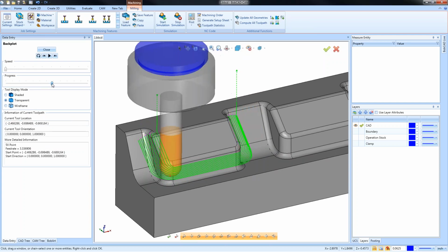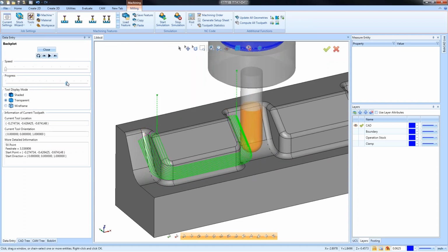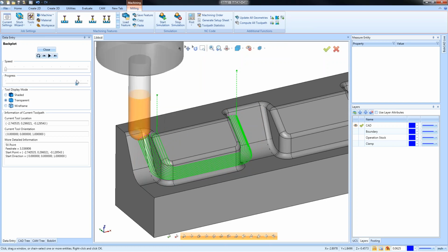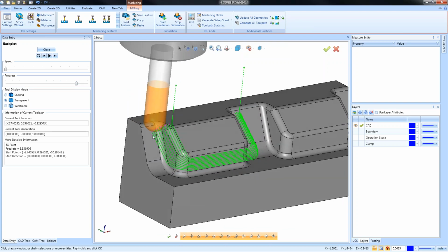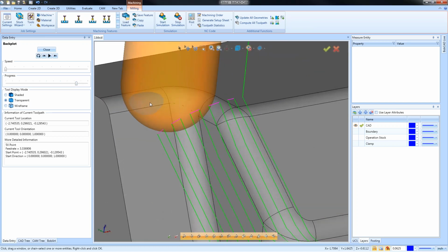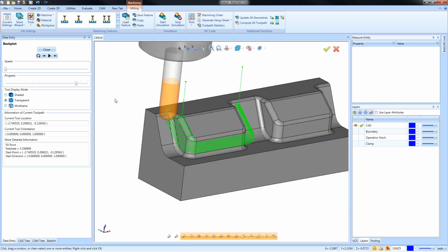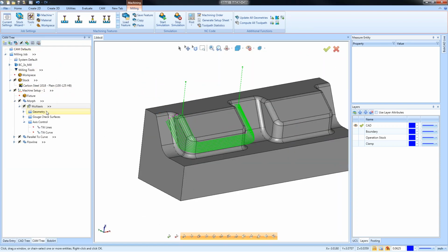Now, something you have to pay attention to is some of these other surfaces here. We can see this toolpath is working its way back and forth. When we did our extension here, you can see how the tool's running into this other surface. When you're working with surface-based toolpaths like I'm working with here, the drive surface and these upper curves and lower curves, these are the things that the software is paying attention to. So these other surfaces over here could be problematic.